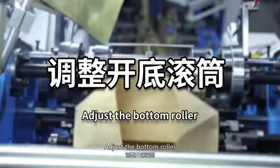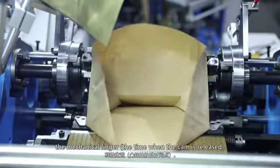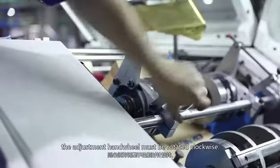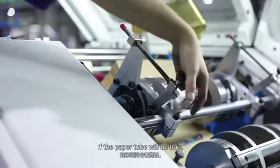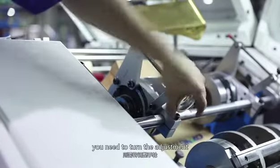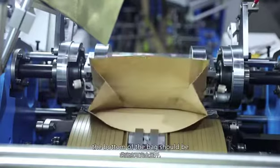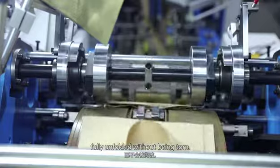Adjust the button roller. Check the release position of the mechanical finger. If the button of the bag cannot be fully opened, the adjustment hand wheel must be rotated clockwise. If the paper tube will be torn, you need to turn the adjustment hand wheel counterclockwise. When the roller is positioned correctly, the button of the bag should be fully unfolded without being torn.